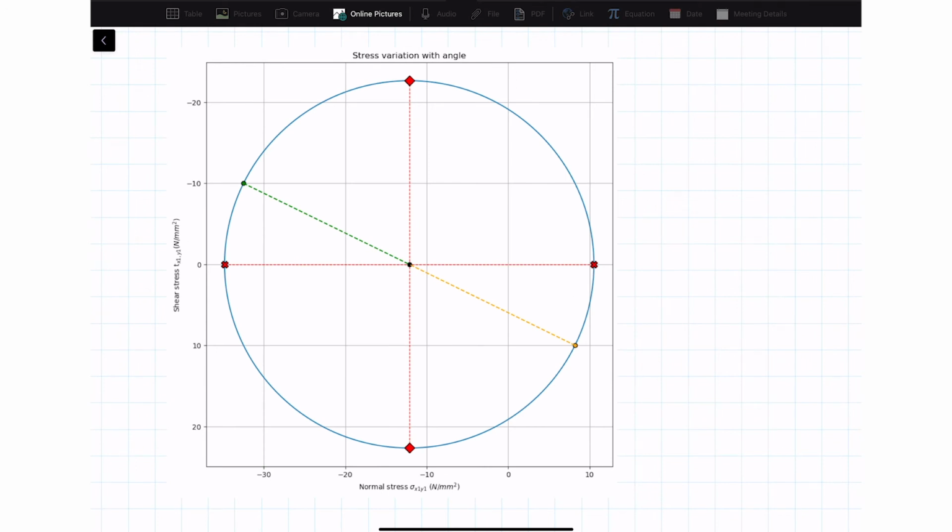All right, then we're on the home straight here. We've got our Mohr circle, and we've identified some key points on the Mohr circle. So the first thing I want to do is just call those out again. So what have we got? We had this point here. That point there was point A. So the stress at that point corresponded to, if I just sketch it out very, very small here, if we have our element here, the coordinates of point A are actually the stresses on this face of our element.